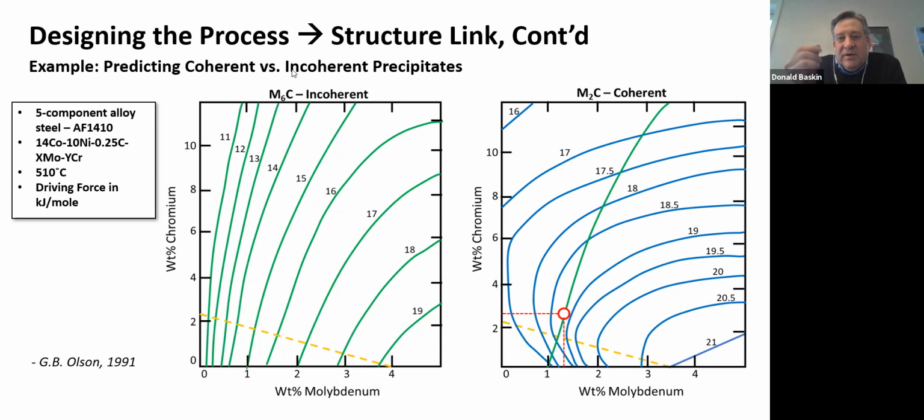So this is really where it is. This is really engineering a material rather than just picking properties out of a table. Now, if you've got the right furnaces and vacuum equipment and refining equipment, you can go back and mix up cobalt, nickel, a little bit of carbon, and you know the exact amount of moly, the exact amount of chromium used to engineer this material to have the maximum strength to density ratio.